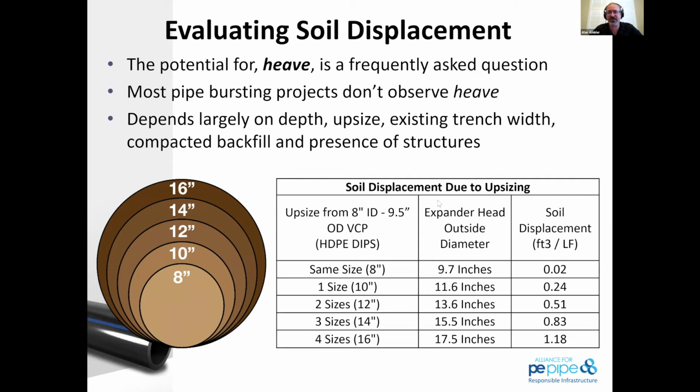So we've worked very closely to prepare some of this material with another contractor who hates talking about this word, heave, because he's never seen it. Although in Florida, sandy conditions where I've done a significant amount of pipe bursting at shallow depths, we see heave and it looks like tremors in some places. Of course that's an exaggeration, but here is a diagram of exactly how much soil is displaced as we go through this. And you can see that when we get into 4 sizes upsize, we are pushing soil. If it's a deeper installation, that soil can sometimes push outwards and upwards and a little bit to the bottom. If it's shallower, we don't have the compressive forces of the soil column on top in order to be able to move through.